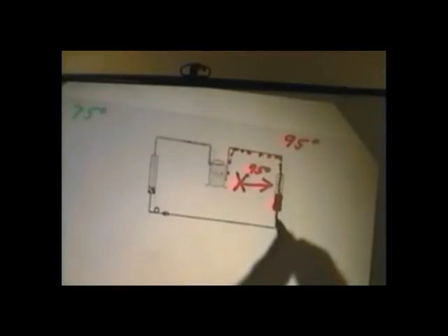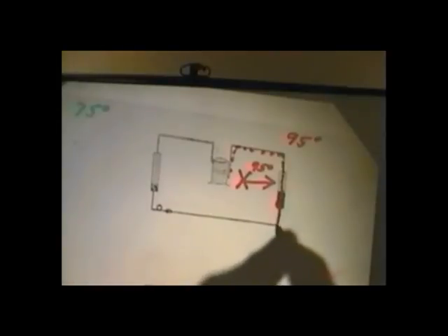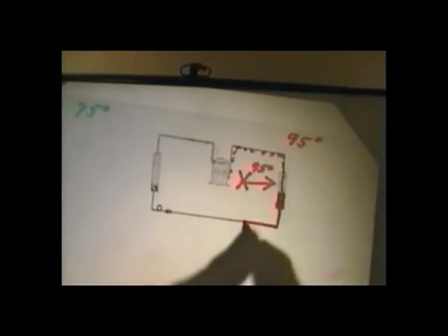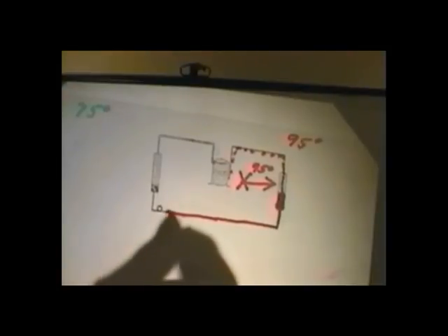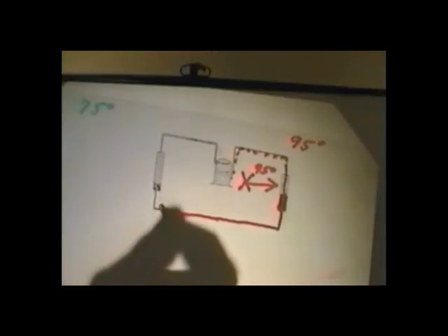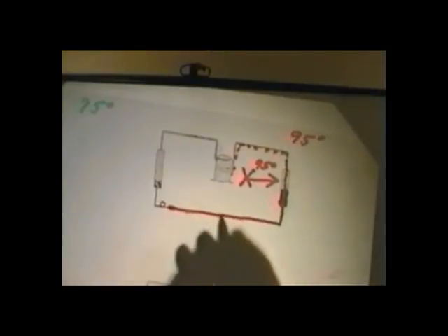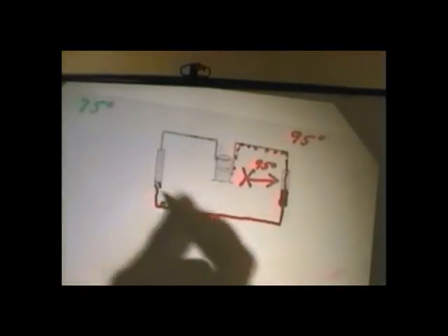Well, then at the bottom of the condenser we have liquid. So we have liquid in that portion of the condenser, liquid in the liquid line, and then liquid in the dryer, which is mounted right before the metering device. Now this is a picture of a capillary tube, but it could be a TXV or a restrictor orifice. And of course, if it's a capillary tube, we have liquid all the way through.